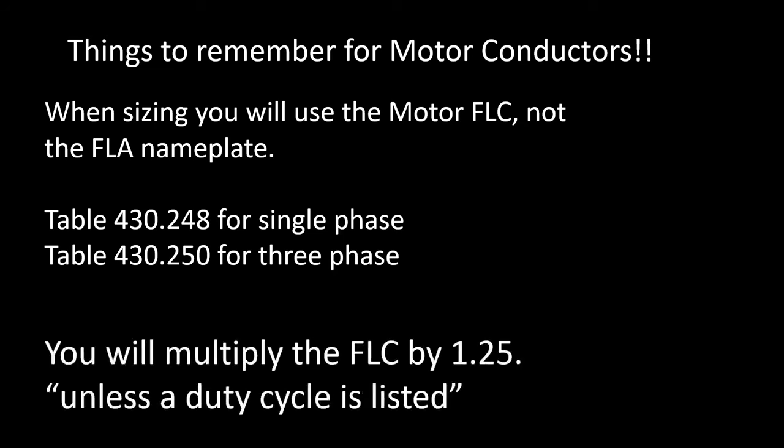Also, the other thing that we have to remember is that we're always going to multiply that FLC by 1.25 when we're sizing motor conductors, unless there's a duty cycle listed. So if there's a duty cycle, it says intermittent use, or it's going to be used for 15 minutes, or it's going to be used for 3 minutes, or whatever it is, then we're going to abide by and play by some different rules, and we're going to dive farther into that next week.